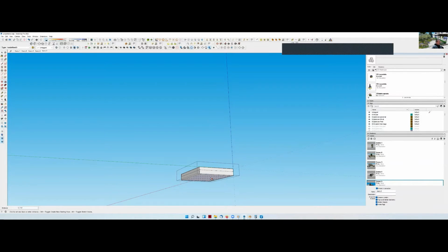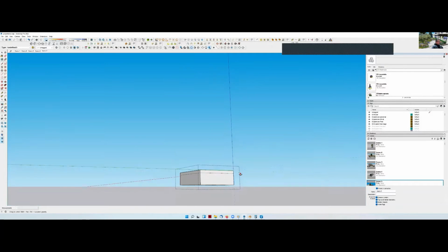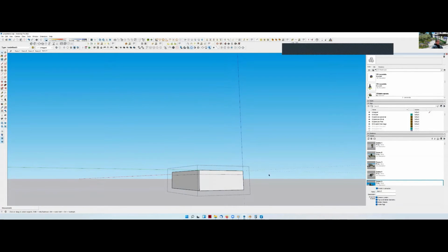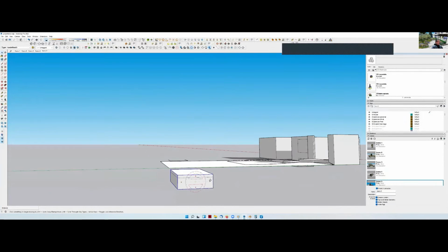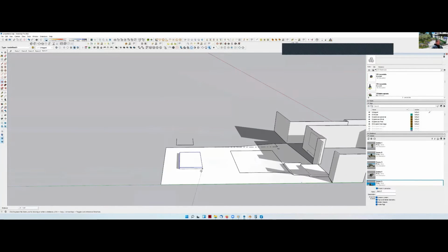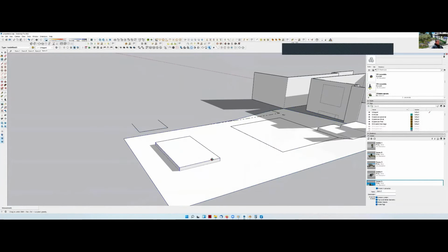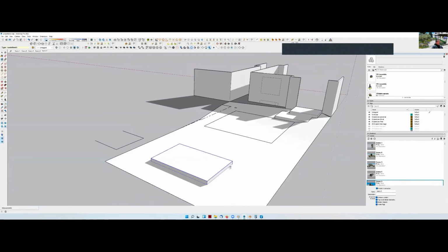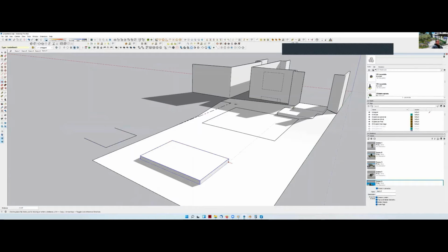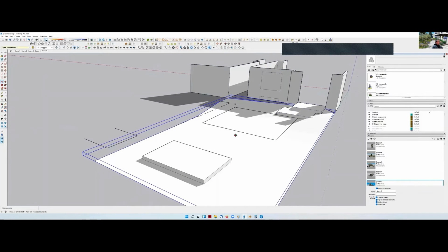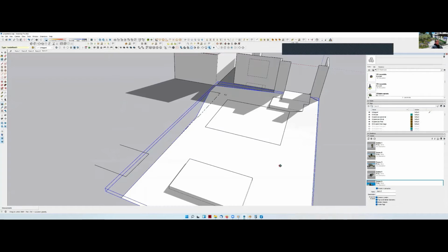You'll just notice a little plus came on beside the tool point there. That means that I'm actually copying that face. So on push and on move, you can actually copy items. So I've just created that 6-inch offset. So it will allow me to make sure I'm snapping in, so it has a 6-inch rise up to give it a little bit more dominance in the space. Then I'm going to line the outside edge here to the outside edge of that side, so it creates a nice little sort of dynamic.